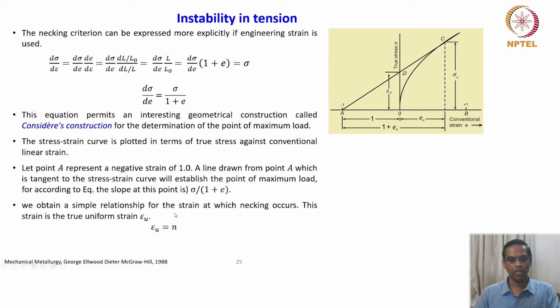This is also a very important relation. So what is the usefulness of the strain hardening coefficient? Strain hardening coefficient can also be looked at. It is equivalent to uniform strain. So the uniform strain is very important in the case of materials which are being subjected to metal forming operations, right? So the measure of ductility and formability and all, some idea it gives. So these relations are very important and useful in that context. Okay.